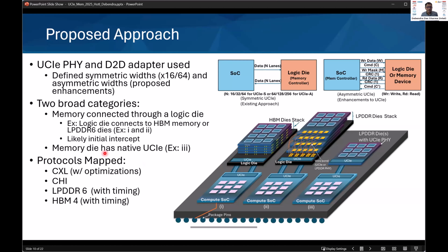The next one is where the memory die has its own native UCIe. That's much more longer term. And this is where we can think of the LPDDR dies, for example, having a native UCIe PHY, right? It needs a lot more changes to the ecosystem. So again, the memory controller can be either on the SoC or on the logic die, and the proposals comprehend both of them. They all have their own plus and minus.